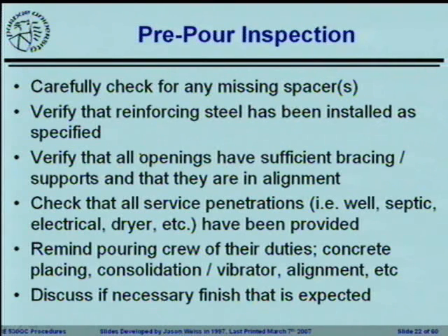The other thing you want to make sure of is when form oil, for example, is sprayed in the forms. Form oil is there to keep the concrete from bonding to whatever the form oil is touching. So form oil belongs on the forms, not on the reinforcing steel. If you want it to bond to the reinforcing steel, you've got to make sure that it's not being sprayed inappropriately or incorrectly. There shouldn't be things like Burger King wrappers and other things like that in the forms.